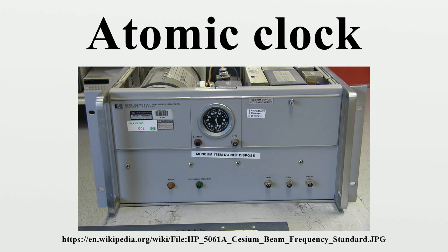Light shift is an effect where frequency is pulled differently depending on the light intensity, which often is modulated by the temperature shift of the rubidium lamp and filter cell. There are thus many factors in which temperature and aging can shift frequency over time, and this is why a gas cell standard is unfit for a primary standard, but can become a very inexpensive, low-power and small-size solution for a secondary standard, or where better stability compared to crystal oscillators is needed, but not the full performance of a cesium beam standard. The rubidium gas standards have seen use in telecommunications systems and portable instruments.